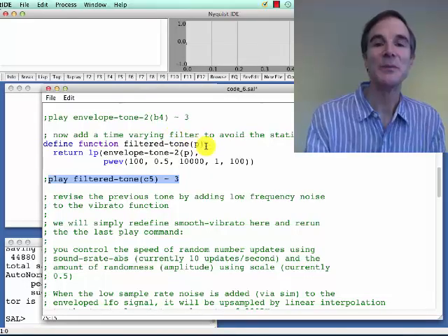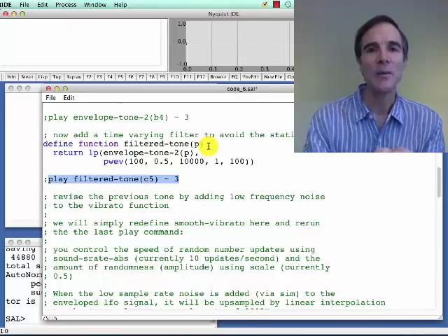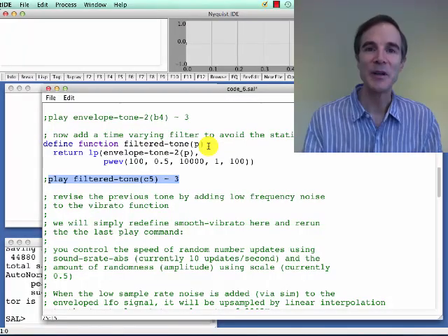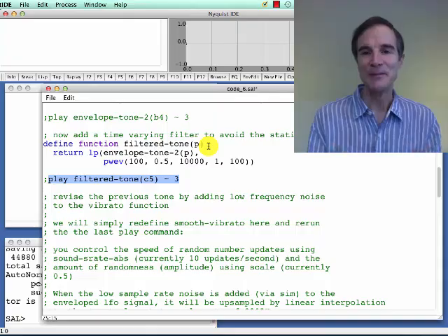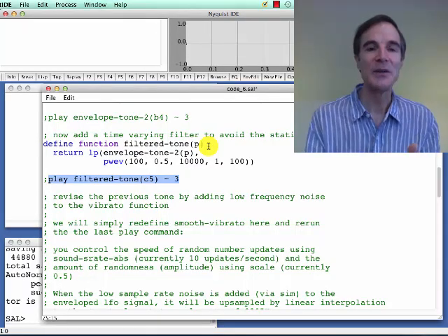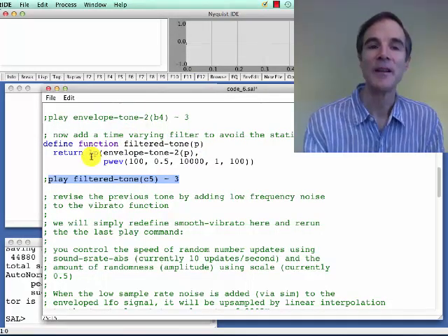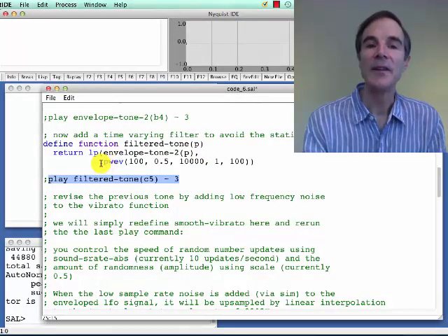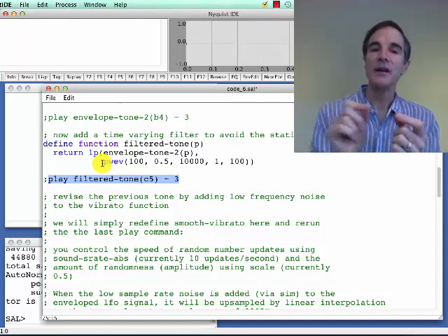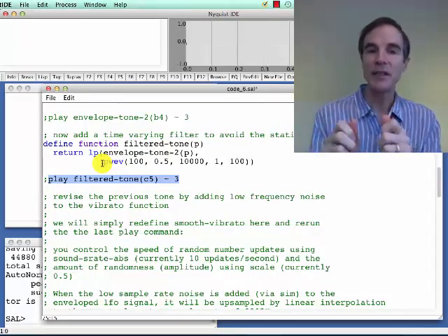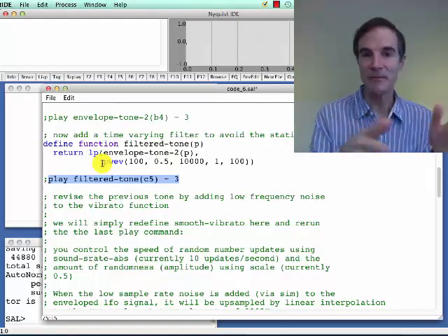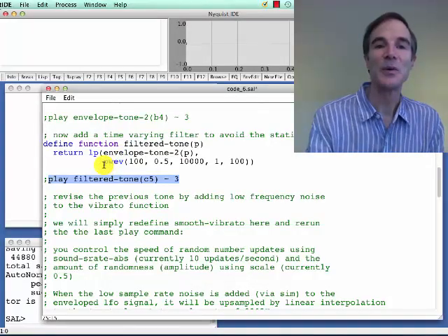The next thing we're going to do, because that sound that we heard I think was pretty harsh. That was a bright spectrum, and to turn a note on with full brightness at the very beginning of the tone gives this kind of harsh mechanical sound. So now we're going to add a filter. This is a low-pass filter which removes high frequencies, and the cutoff frequency, the frequency below which we pass sounds, is controlled by an envelope.